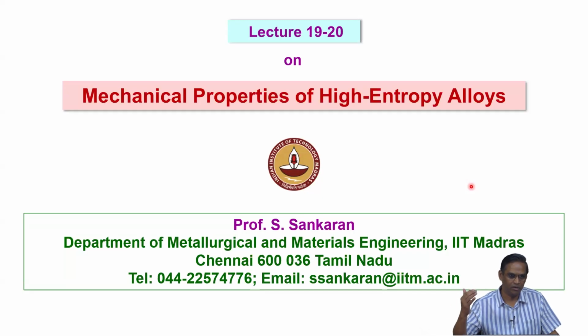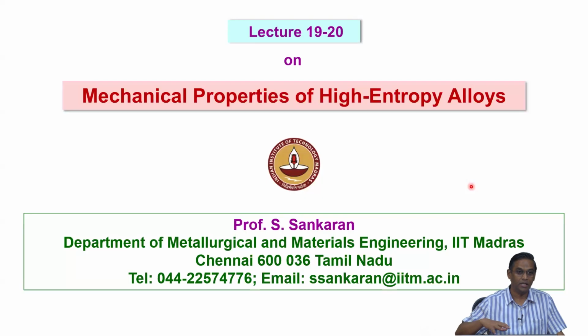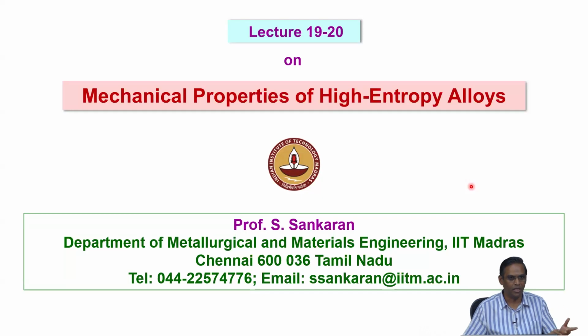But when the stacking fault energy is low in a material, the defect structure will try to rearrange only in a planar fashion. So you will have a planar array. Instead of a cell structure, which requires three-dimensional mobility of dislocations during plastic deformation, in a planar slip you form a network of dislocations, possibly a hexagonal network or a line of slip bands. So that means the three-dimensional mobility is restricted.